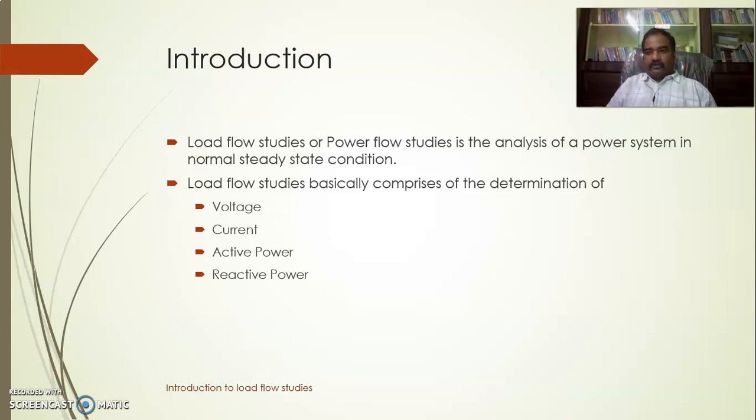Out of these 3 variables, we consider the voltage and the power as independent variables, and the current is determined if we know the voltage and power. So in the next course of action, we will eliminate the current and solely concentrate on the complex voltage and complex power while dealing with load flow studies.